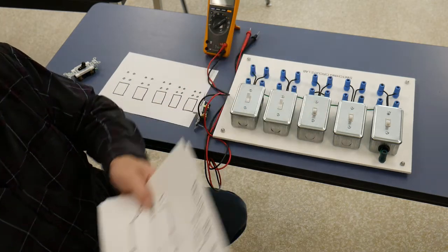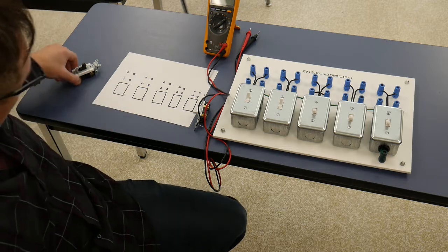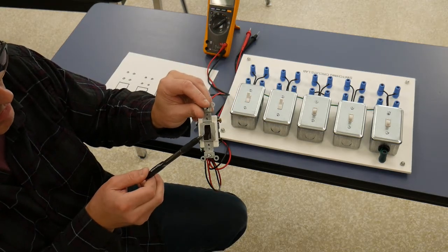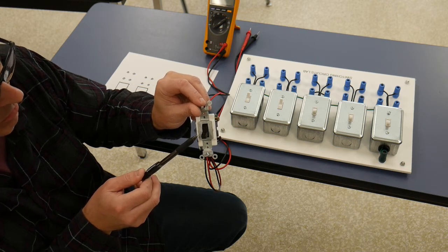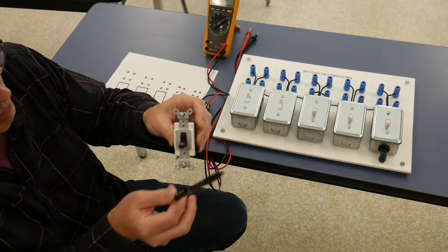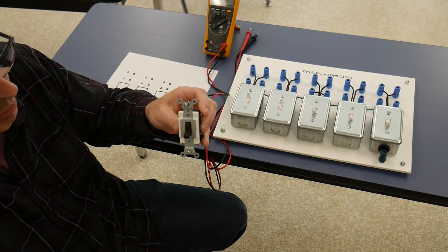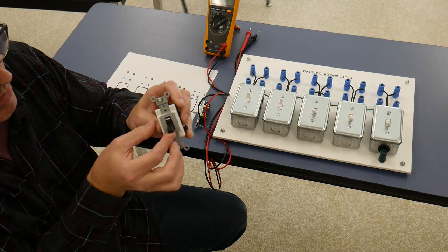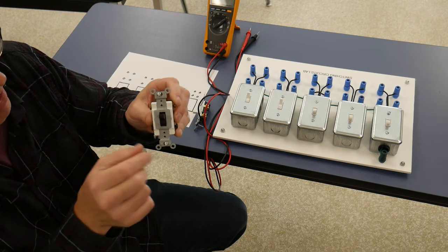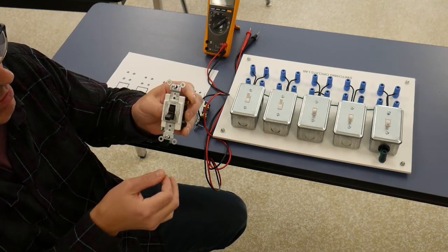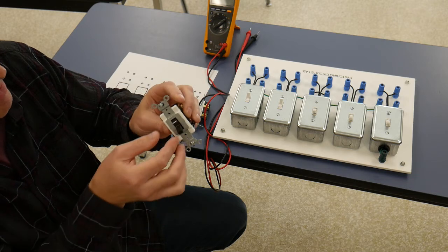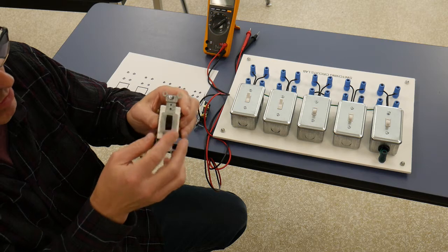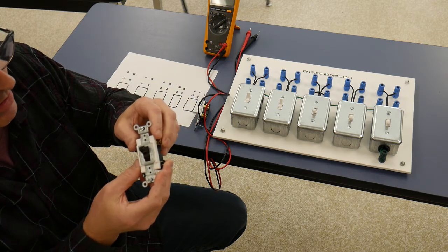Okay, so that switch, how it looks or appears, is something like this. Now please note the difference, I know this is brown or a black compared to all the other ones that were white, but the biggest difference with any switch that only has one way of either opening or closing, they will always be labeled on or off for the most part. Okay, either that or they have dots or a 0 on them. Okay, so that is a double pole single throw switch. In other words, one movement opens or closes a pair of line conductors.